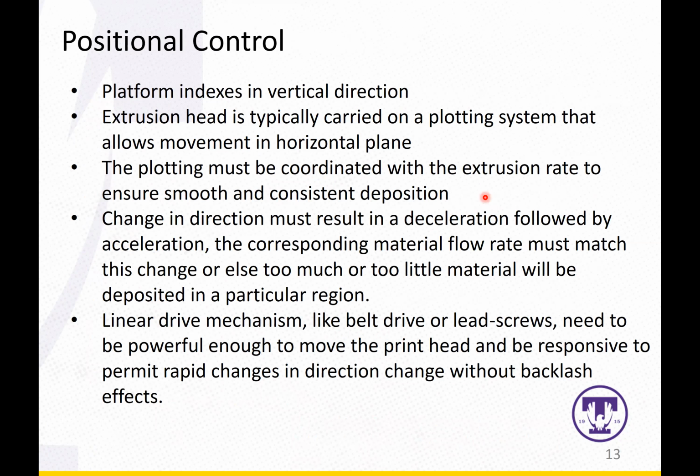So yeah, that is why for some low-cost fused deposition printers, the printing quality will be pretty low, because, to save cost, they just use cheap motors or belts, and it turns out they cannot control the motion quite well, and there will be some distortion generated in the printed layers, right?